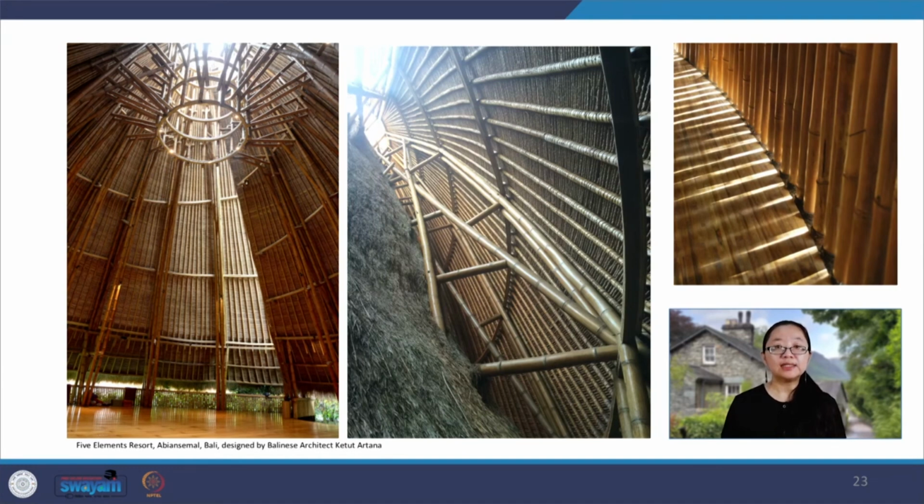One of the buildings seen in the picture is the main hall, which takes on a split conical shape, a transformed rigid arc shape with round plan. The roof structure, made of bamboo canes, has a crown-like ring in the middle which acts as compression ring to bound the roof. The walls are open, with bamboo canes aligned vertically in harmony, tied with ropes. The building is used for yoga practice, meditation workshop, and etc.